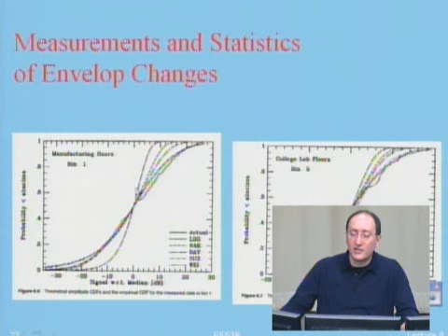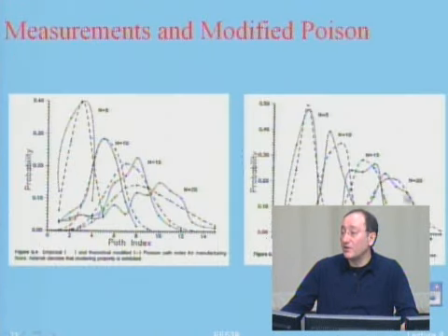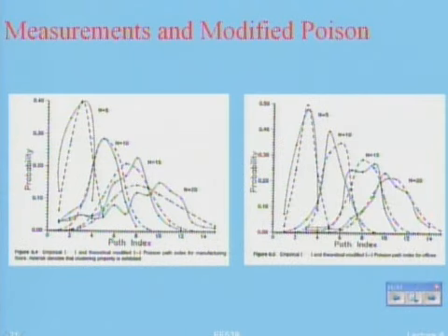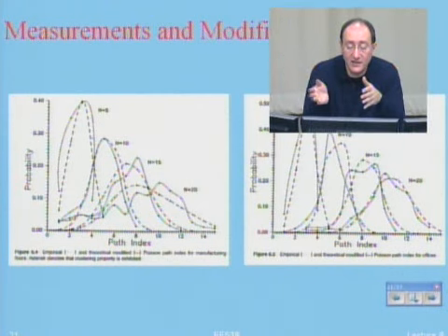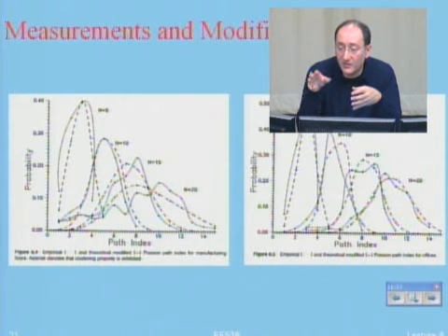So this is one of those advanced areas in channel modeling. Now, the other issue was the issue of arrival. Poisson arrival is not correct, and that was the conclusion that we got by examining, for the NSF, Saleh and Valenzuela's work. We showed that arrival is not Poisson, it's modified Poisson.